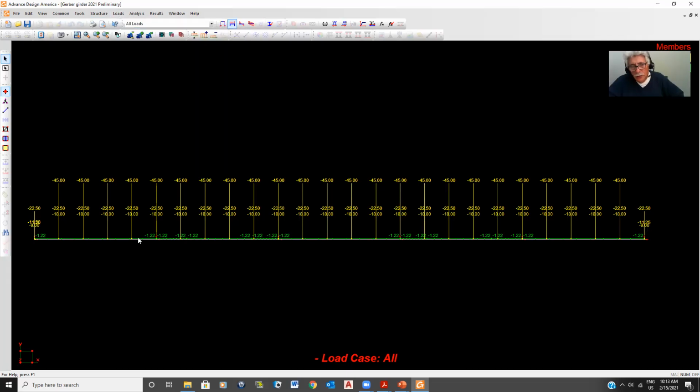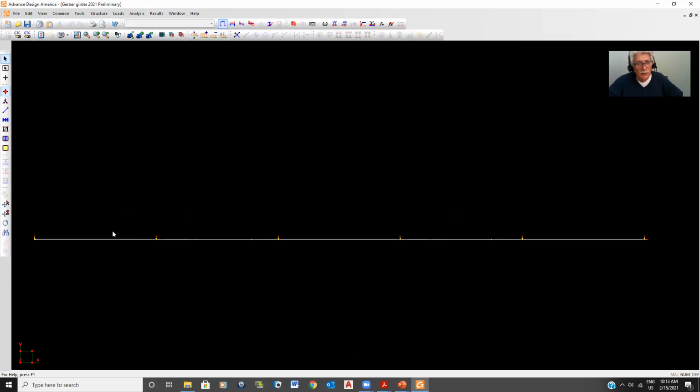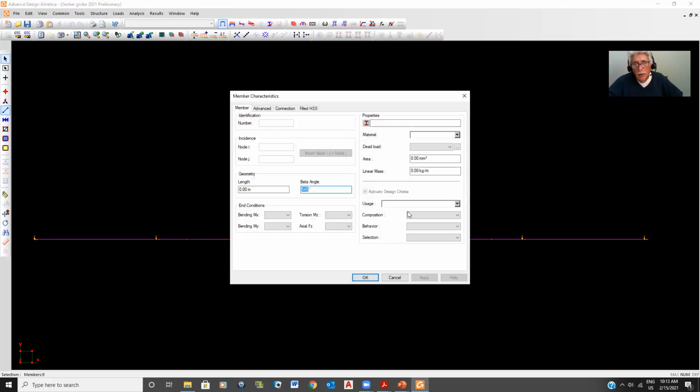Okay, so the only thing you have to do is go back and pick all your properties here. In other words, you're going to have to go back to properties, Omar. You're going to have to pick all your things here, right? You pick them all. I'm sorry, I should have picked members. Okay, pick all your members. Right click on it. You go to properties. And here you're going to have to make sure that you highlight dead load. You understand?